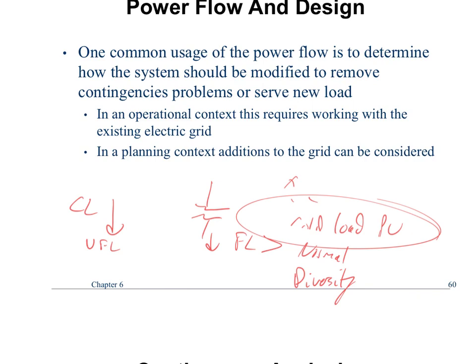But black start capability is very difficult, right? There's no power. So how do you get a big generator online without actually having a lot of power? Well, in New York, when they had the blackout, they actually started the entire city off Unit 2 in Astoria. How they did it is they barged up a generator from the Navy. It was on a ship and was maybe 5 megawatts. They barged it up the river, tied it off next to Astoria Unit 2, and then they brought Astoria Unit 2 online.